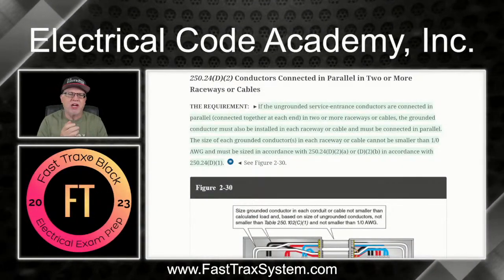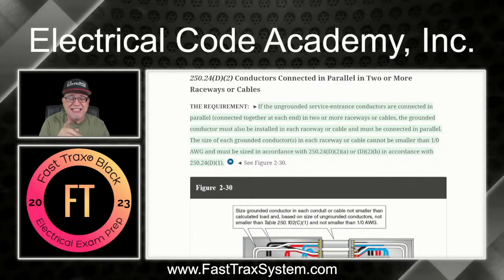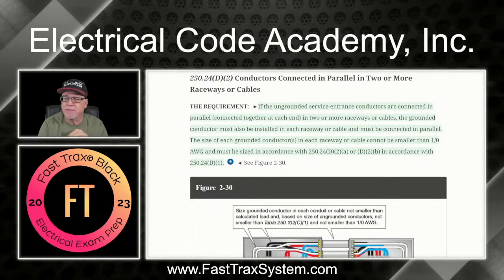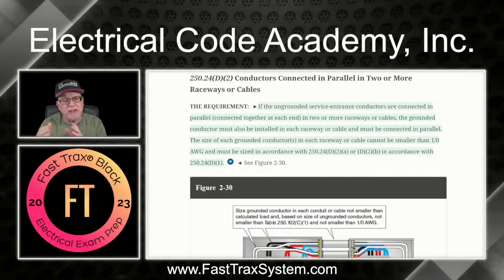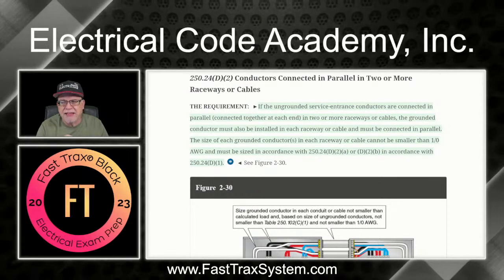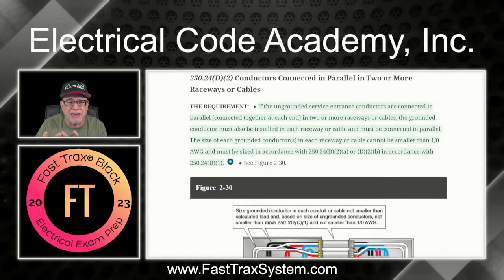All right, so what we've done is we've worked our way up to 250.24(D)(2). Previously, we did (D)(1), and that's single raceways when sizing the grounded conductor, minimum sizing. And now we've moved up to (D)(2), which is parallel, 2 or more raceways or cables. Now, I would be remiss if I didn't remind you that this is going to give us guidance on the minimum size of a grounded conductor.